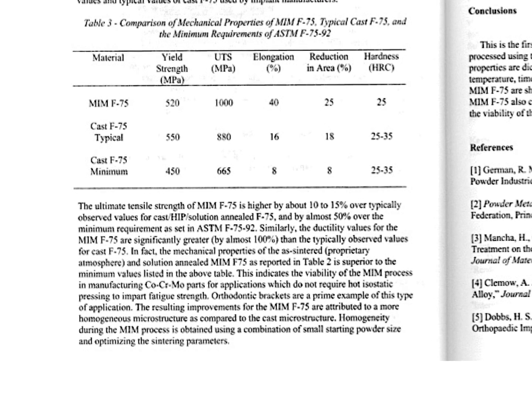And so, yeah, we think about hardness as being important, and certainly it is. Ultimate tensile strength certainly important. Elongation, the nice thing about that, what that is saying is that the metal injection molded has fewer flaws or smaller flaws. That's what that is really saying. That elongation is better than what we get, so it means it's less flaw sensitive. All right, and so there's a bunch of things here talking about how this is important,